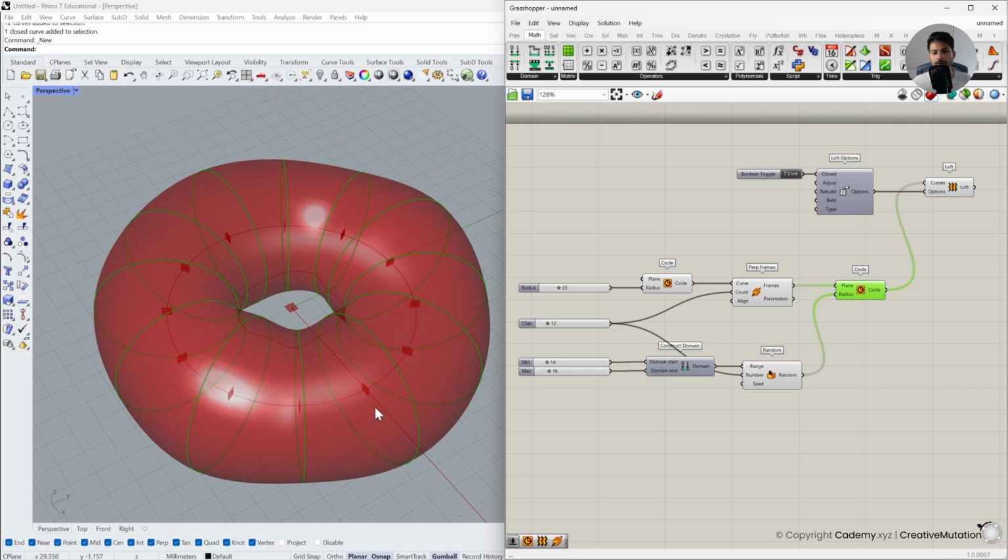Okay, we can choose where the point is gonna be, and we're gonna connect all these points together to create a curve, which we will use to part this base donut into two halves. Okay, now rather than using a fixed place for the point, we're gonna randomize the displacement of the point across the circle. All right, so let's see how can we do that.